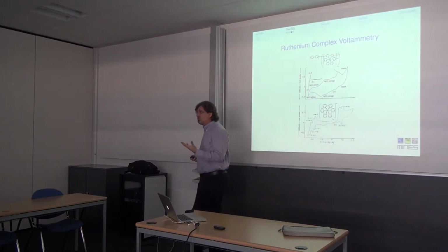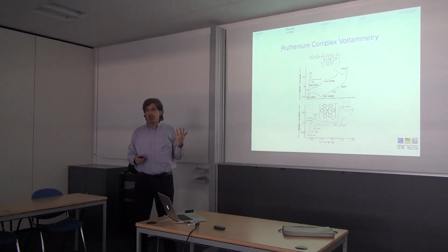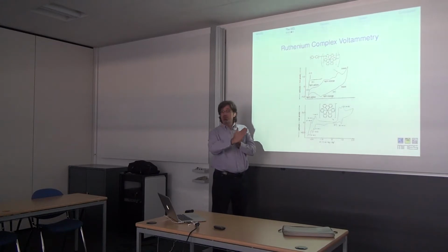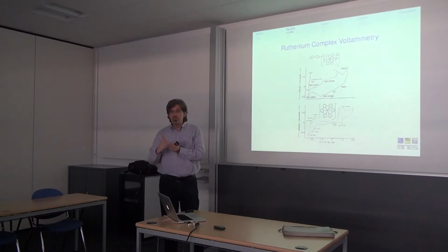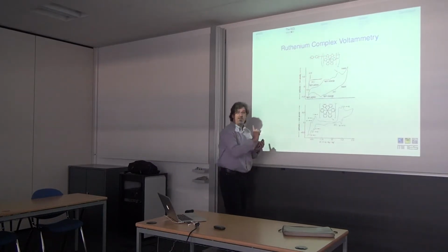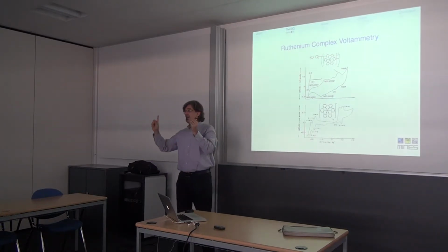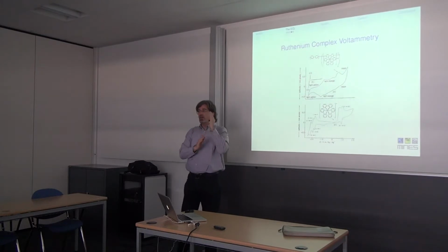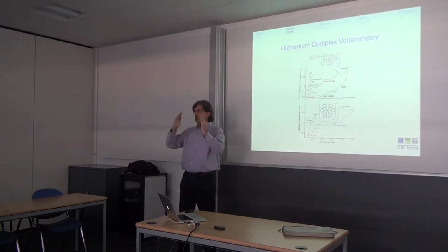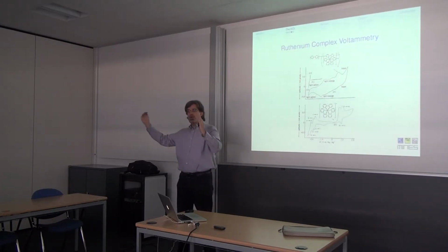So, the emission of the orange light, because what I'm doing is to stimulate using the counter electrode, so I induce my voltage inside the cell, and I do what is named cyclic voltammetry. So I start from -2, +2, I go back and forth, -2, +2, back, -2, +2.